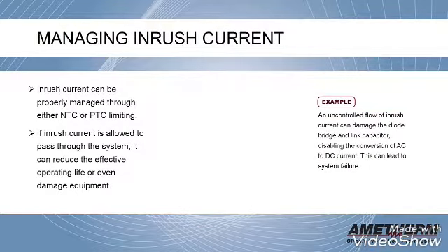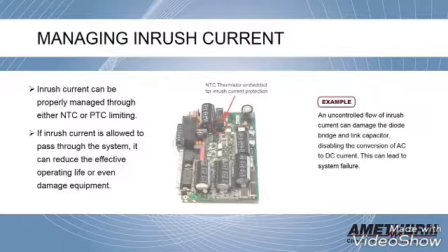Next, let's discuss managing inrush current. Inrush current can be properly managed through either NTC or PTC limiting. If inrush current is allowed to pass through the system, it can reduce the effective operating life or even damage equipment. Let's look at an example.